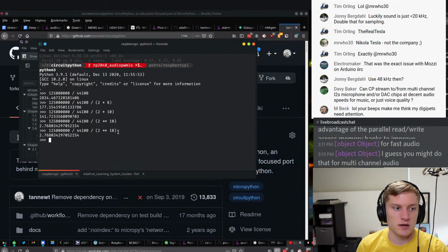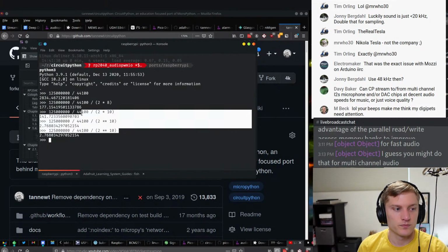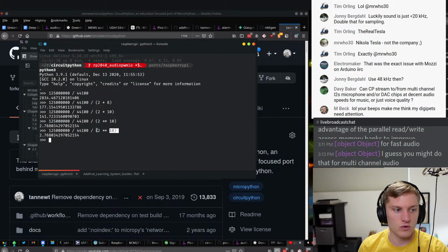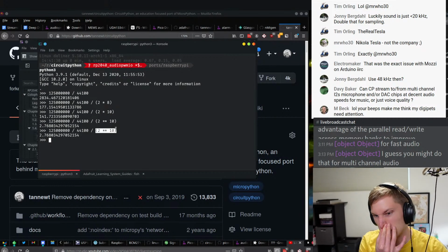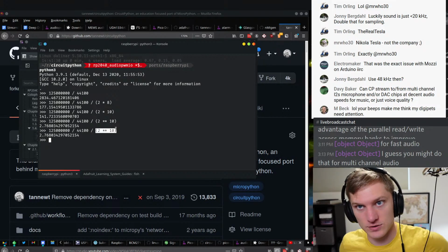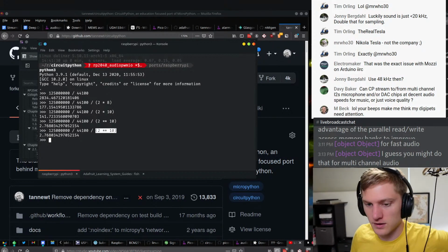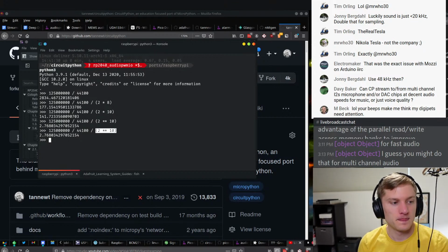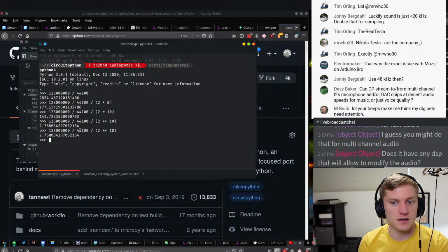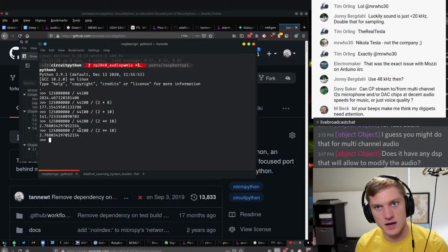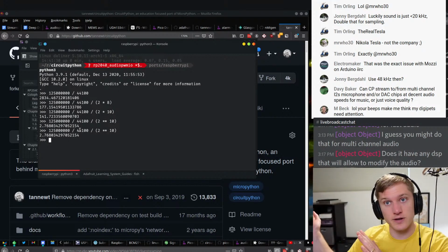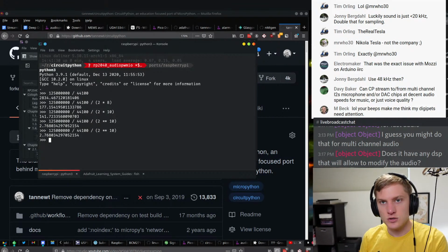So yeah, the challenge with PWM out is that you lose resolution depending on what your top value of the PWM is, which is how many bits of resolution you get in the value. I think this is going to be the major limiting factor to audio PWM IO, but it's nice that the I2S doesn't have this problem because it's just sending a digital value out. So it costs 2 cycles per bit of resolution.